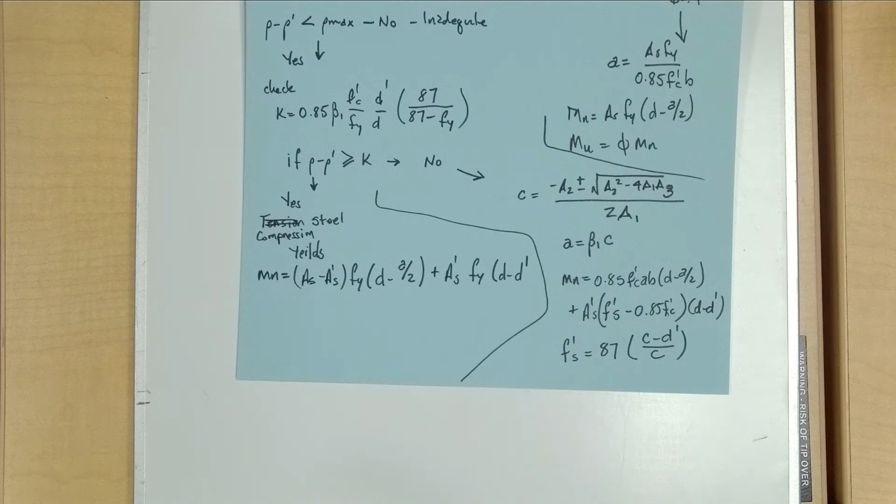And then after those two steps, we would multiply that by the phi factor for both of them? Yes. Okay, and then also on the left, would that be in inches, the M_n? M_n would come out as kip inches. Okay, so do you want that in inches? It doesn't matter.